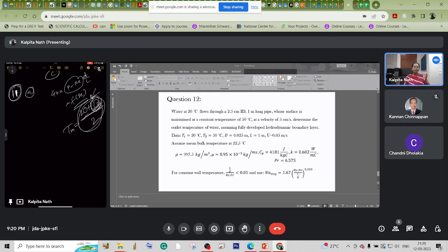That's why when we do the overall mass flow rate, it will be in the cross sectional area direction. We consider that as a plug of fluid, right? Yes. Otherwise, if we don't consider it as a plug of fluid, then the temperature may change, right? So that's why we consider it as a plug of fluid, and that's why we can use m Cp delta T. But it will be in the cross sectional area direction, so the area will be pi d square by 4.